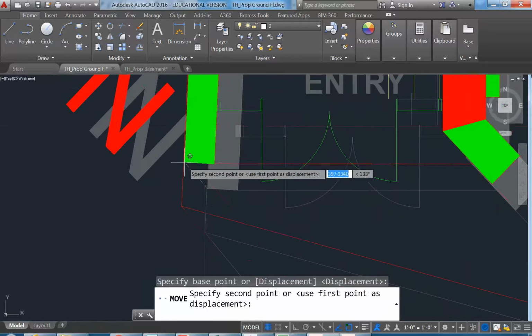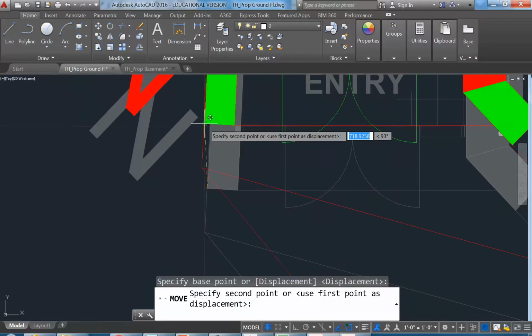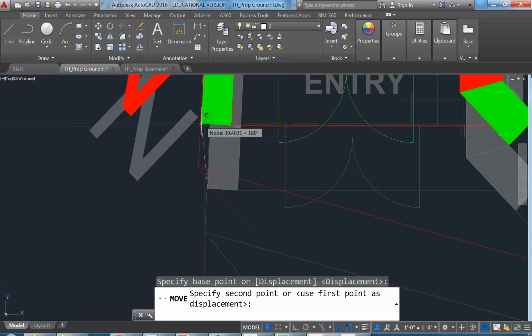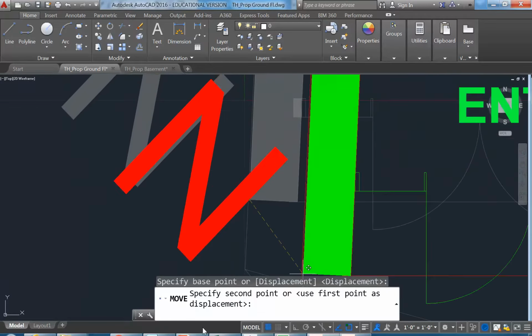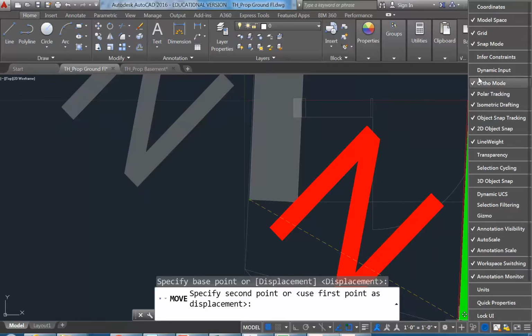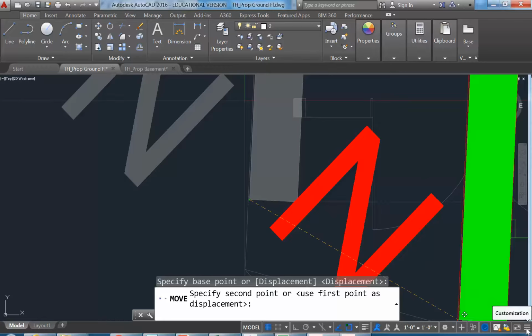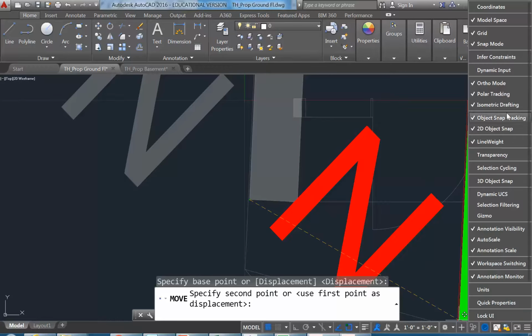And so then to type in the origin, we need to use a special option. You actually have to go to the list and make sure dynamic input is visible. Clicking on the three lines in the bottom right corner, you'll see you've got an option to turn on dynamic input.